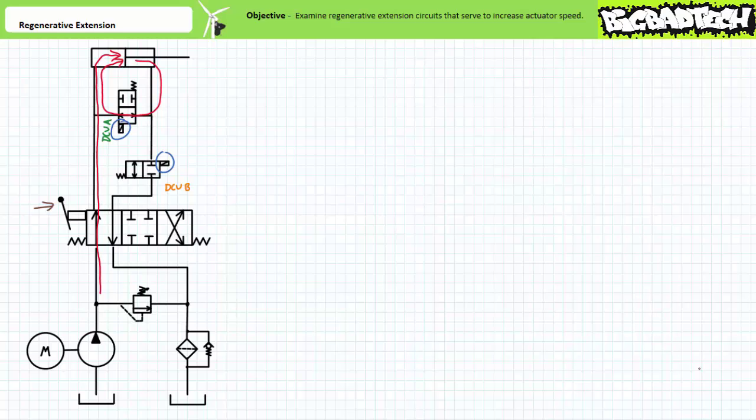Before we close up shop, allow me to crush your dreams. No, there is no such thing as regenerative retraction. I know some of you are already scheming of cunning ways to create and patent a regenerative retraction device, but good luck doing so, since the volume differential inherent in a regular double-acting cylinder only makes this method work during extension. Yes, you can put all sorts of crazy secondary components like intensifiers and accumulators and more directional control valves and pilot-operated check valves to kludge together something that kind of does the same thing, but my response to all this silliness is why?